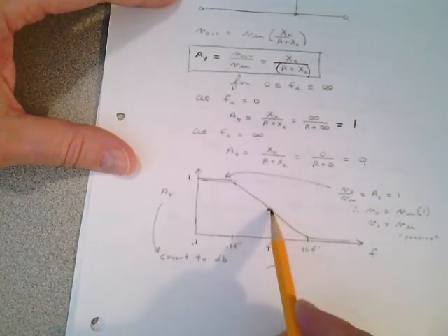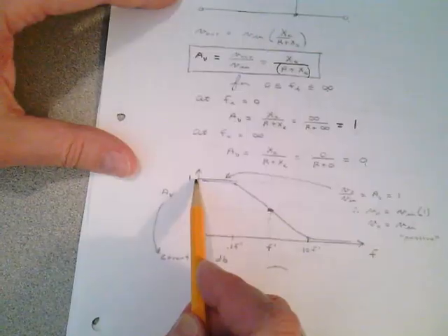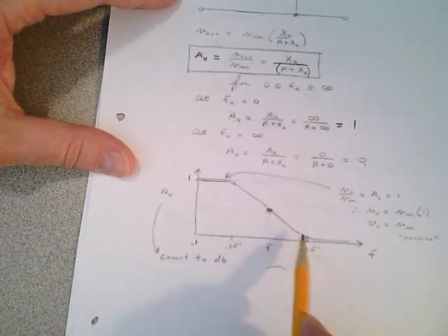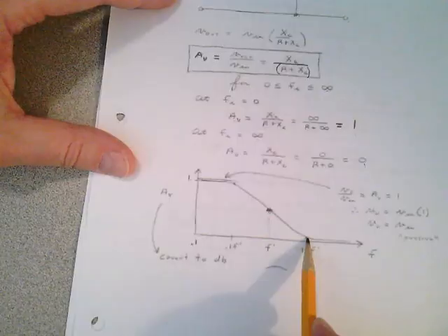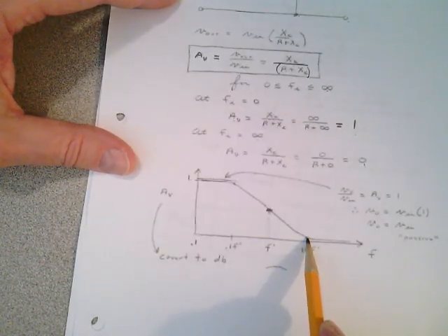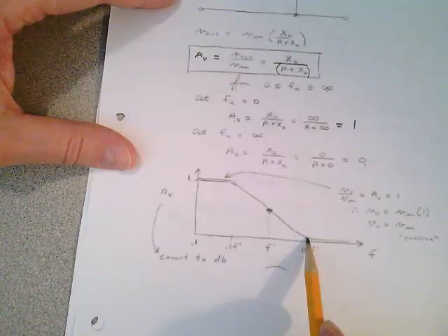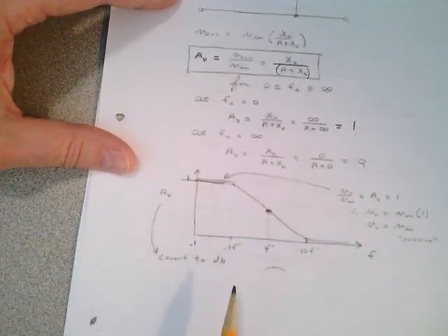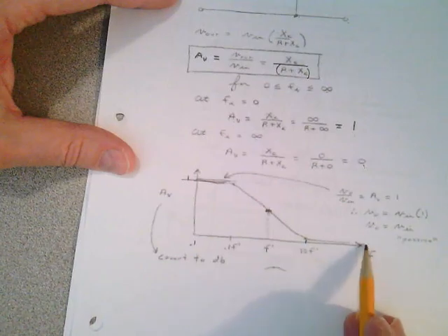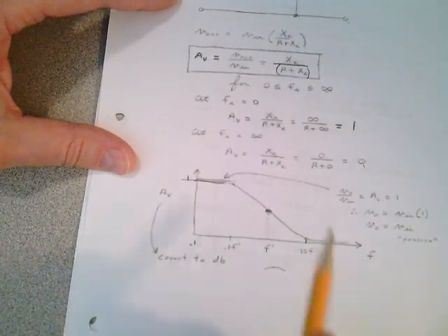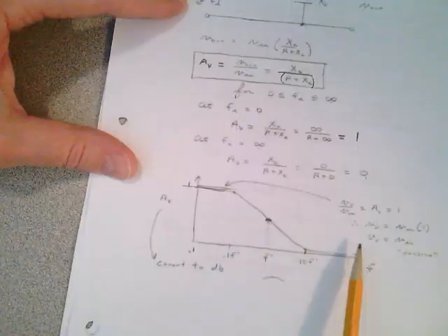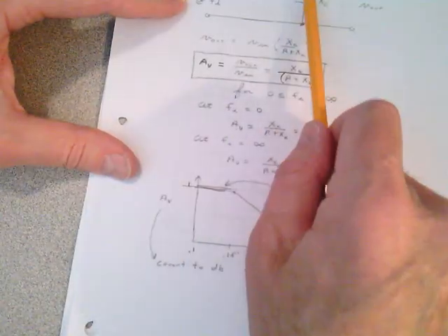So at 1/10 the frequency down, you already got the full effect of the filter, and at 10 times the frequency up, the effect of that filter has diminished, or has run its extent. Notice this: at the low frequencies, you pass the signal. At the higher frequencies, you kill the signal. That's what a low pass filter does. It passes the low frequencies and it kills the higher frequencies. Why? Because that shorts out.